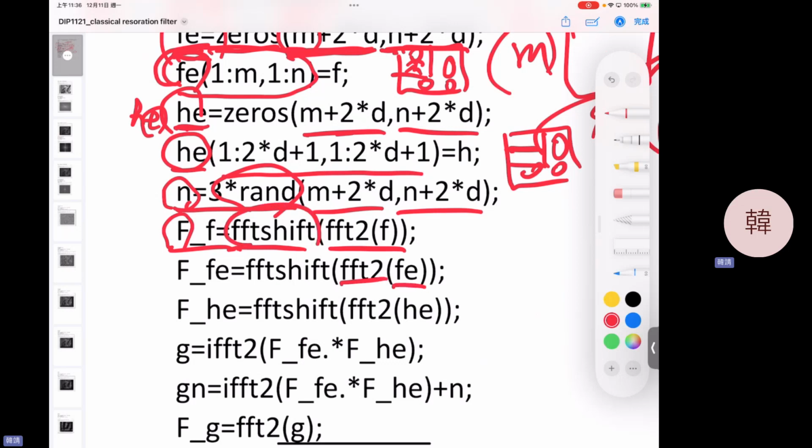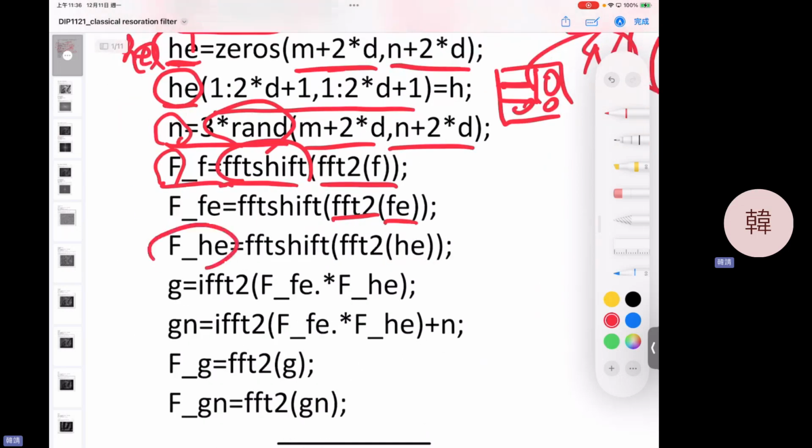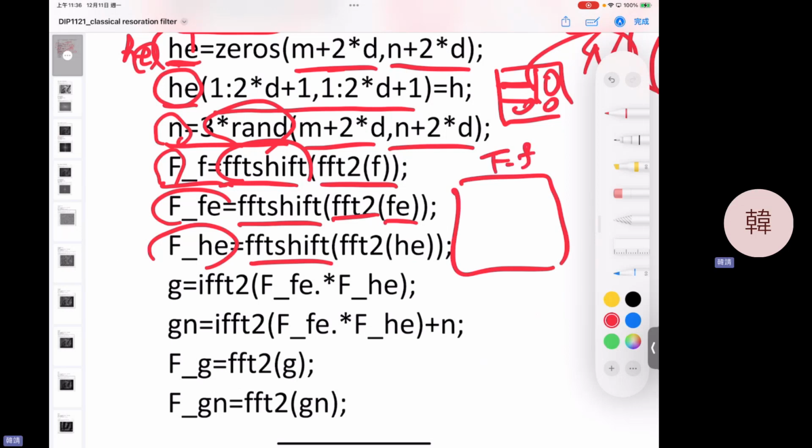And then why do we do FFT shift? Because you want the low frequency component in the center of your output. You can see it clearly. So all our Fourier transforms have performed FFT shift first. Remember that, okay? If you look at your frequency components, in the frequency domain image the low frequency part is in the center and high frequency is at the corners. If you don't do this, your low frequency will be at the 4 corners, so it's not obvious to observe.